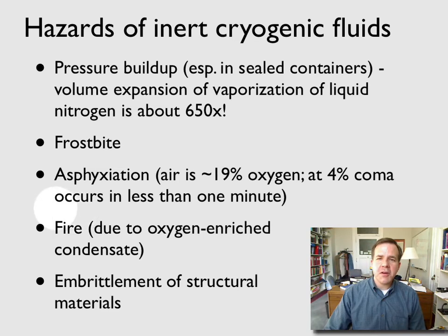One risk or hazard of inert cryogenic fluids, which we don't sometimes think about, is the risk of fire, particularly with regard to certain organic compounds. The reason is that the low temperature associated with the cryogenic fluid can cause enrichment of the atmosphere with oxygen, or it could actually cause oxygen to condense out of the atmosphere, and that can then create a very oxidizer-rich environment, with then the right fuel and the right ignition can lead to a fire or even an explosion.